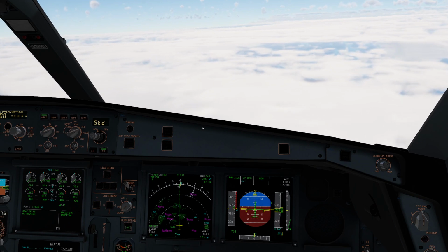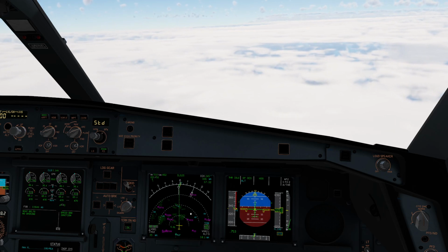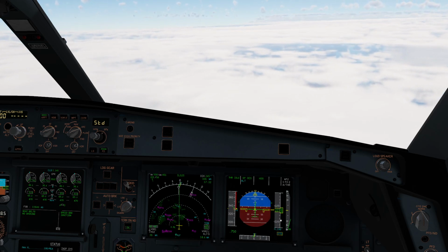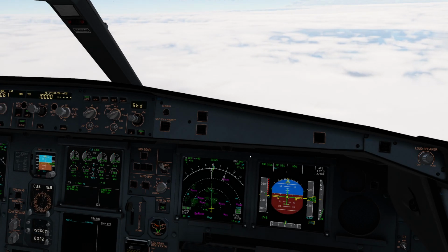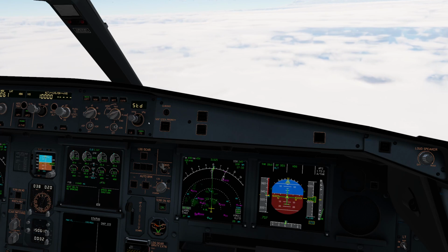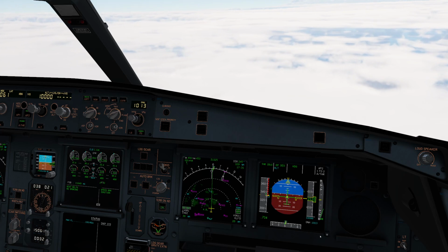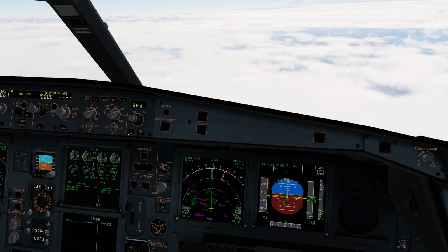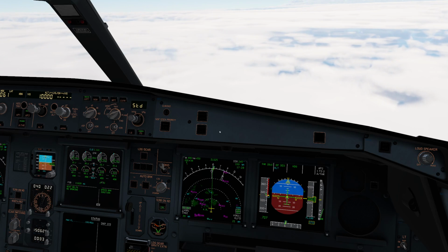Okay, at this point we would mostly communicate with ATC, get the local QNH. Keep in mind we have to make sure that we descend to an altitude of 10,000 there, and not a flight level 100. So if we can get it, then ATC can tell us the minimum off-route altitudes and the QNH. So let's say today is QNH 1013. We don't need to do this, but we need to make sure that we get below 10,000, so we can stay on flight levels as well. Okay.